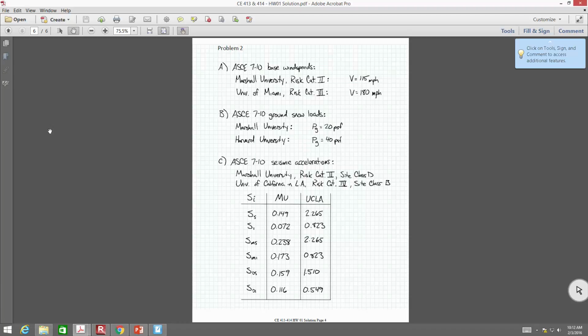Suffice it to say that if you get snow events that are very significant and go above and beyond, they can throw your data set. Just take a look at snow load maps and snow load values from one edition to the next. They change, and they change because we have more data. More data gives us a better picture of what we're looking at. Does that help out? This is good stuff. Seriously, this is good stuff.